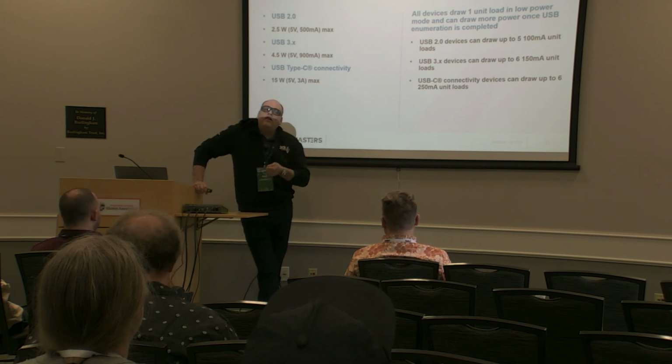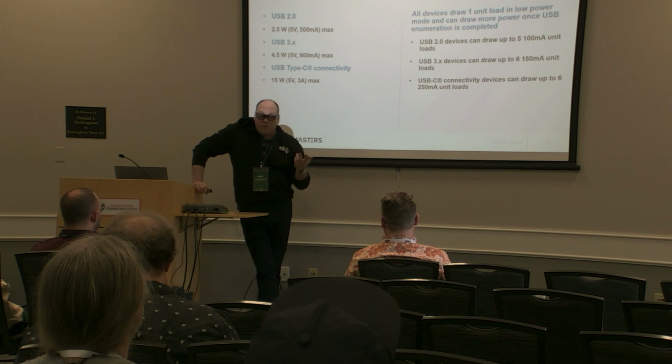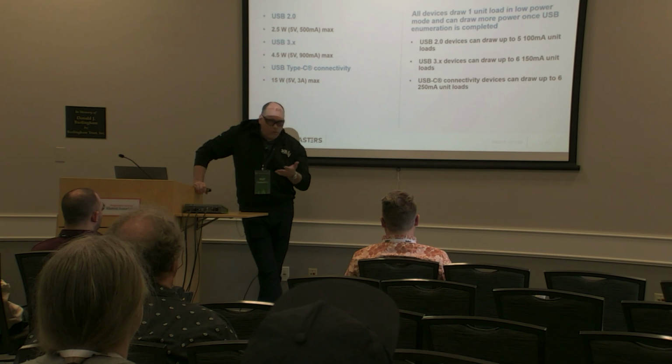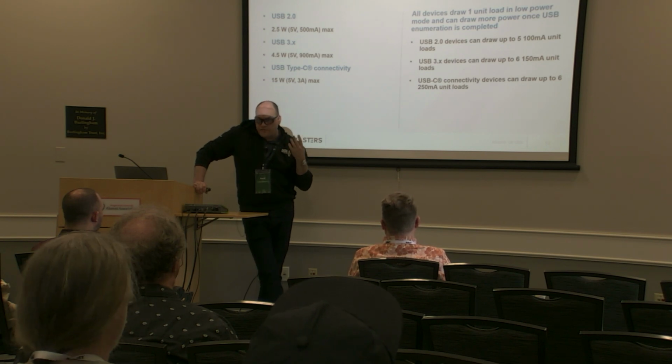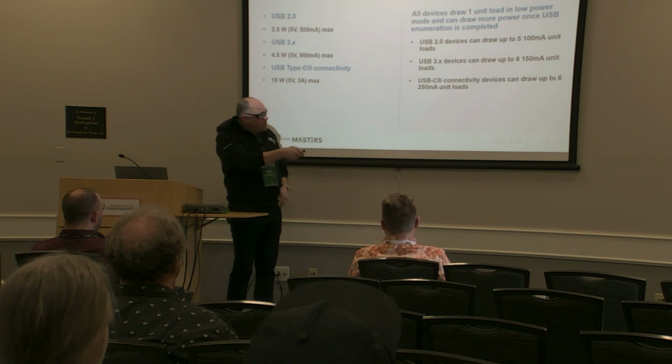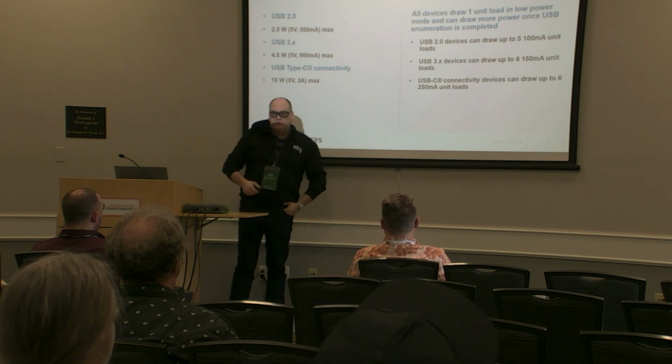Okay, so I plug in another 250 milliamp device. How much is it going to get? 300, right? It needs 300, so it's going to get 2 more loads. 2 loads and 2 loads, so we've occupied 4 loads of power. How many loads are left? 2, because USB 3 will only give you 6.